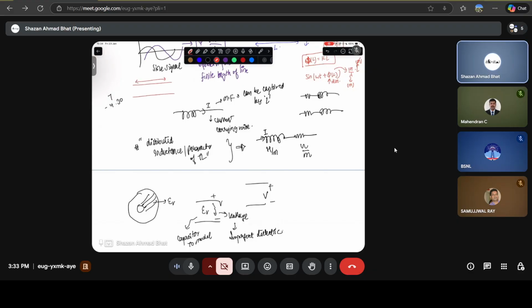Now what is happening is that you need to understand, if you have a wire of length L, when these electromagnetic waves flow, how are you going to model this particular wire to understand the voltage and the currents? And when you model, you have to model it from the circuit perspective, because you have to understand it in terms of resistances, capacitances, and inductances, because that's what we basically know.